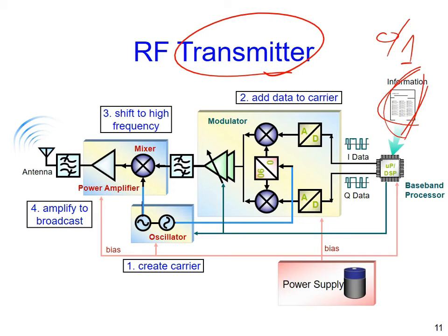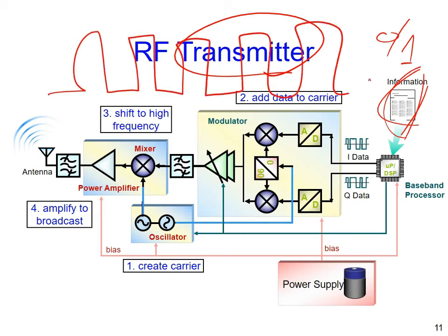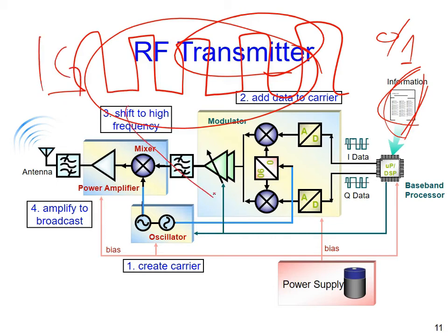Okay, you cannot transmit a digital waveform just like this. Sorry, the telecom company will kill you, or the government will kill you, because if you transmit anything like this, according to Taylor series expansion, right? If it is 1 gigahertz, then all the harmonics, 2 giga, 3 giga, 4 giga, all the way, will also exist in the air. You will interfere with all the other radio stations, all the other companies. It doesn't make any sense.